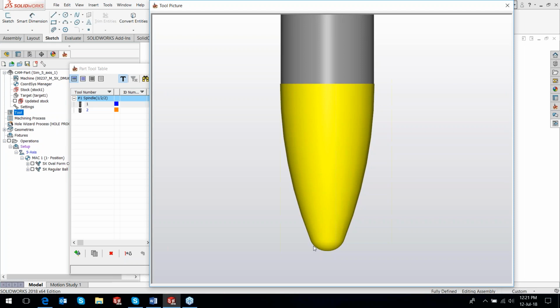when you're doing a scallop calculation on a part, let's assume we have got a part with a large radius and we would like to machine that. If I use a tool, let's say this tool's diameter is 16. So if I use a 16 ball nose, the front of the radius will be R8. It will be a small radius. Now, if I want to use the R8 radius and generate a scallop of, let's say, 5 microns, I would probably need a step over of about 0.3 or 0.5. Between that, I will need a step over to generate a scallop of 5 microns.